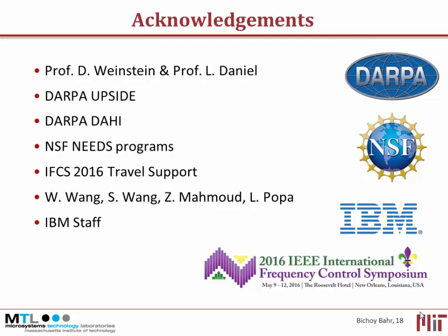If you consider packaging, what will happen is that the entire device will get strained. And so we expect all these dimensions will look slightly elongated after the strain. So we expect some shifting in the resonance frequency. But of course, this is something that can be calibrated for. Beforehand, we can do a prototype, fabricate it, package it, and estimate the frequency drift due to the package. And then when we design, we know what will happen after packaging.